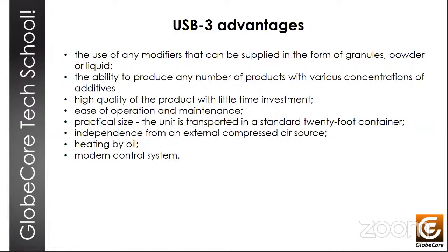To simplify the control, what we do is we add a pneumatic diagram to the control cabinet. It's a simplified process diagram with signal lights that allow the operator to quickly see what's going on inside the plant. The plant itself is run and monitored by a software algorithm embedded in the PLC, and this allows you to quickly customize the process settings. And it actually can be configured via the internet remotely, and it's very reliable, this PLC, and it does significantly speed up the setup of the equipment and commissioning and startup and whatnot.